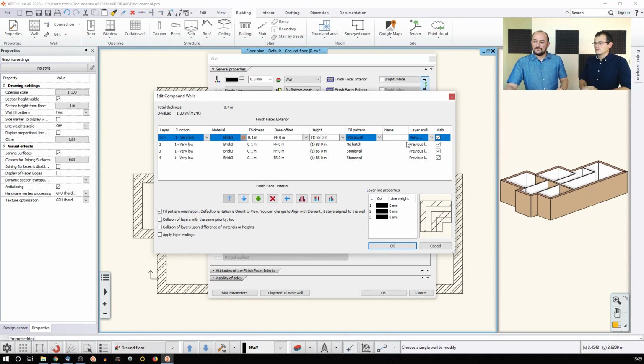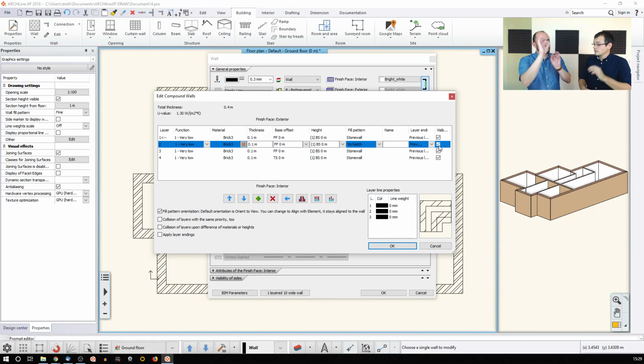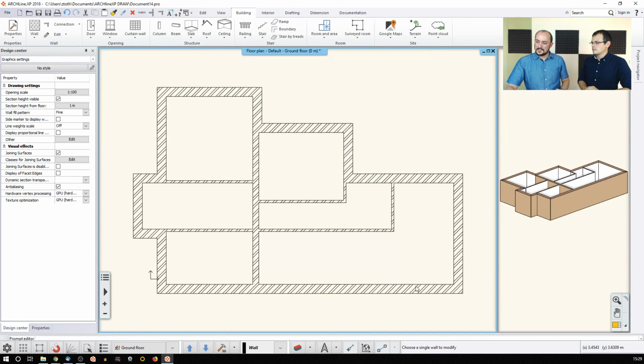So for example, if this is an air cavity, you can turn off the visibility, or instead of that, sometimes we just simply use the visibility, because in intersection sometimes we would like to see some hatch of the air cavity as well. So I turn on the visibility, but I use a material called air, which is a visible material, but it's completely see-through, so you can use it just as well. You turn off the layer visibility.